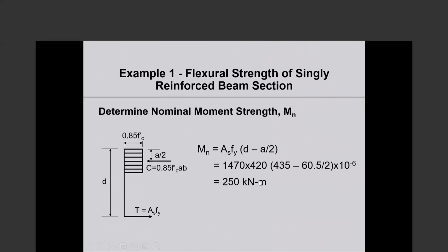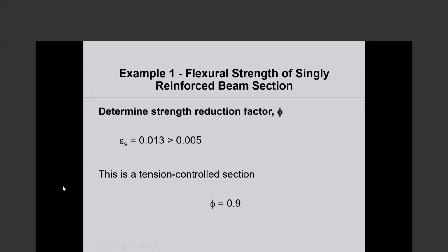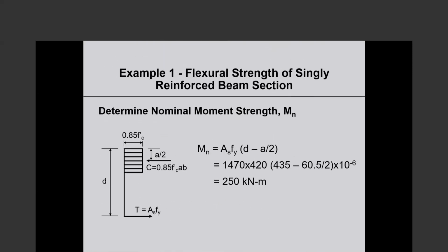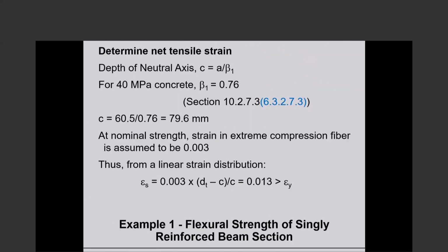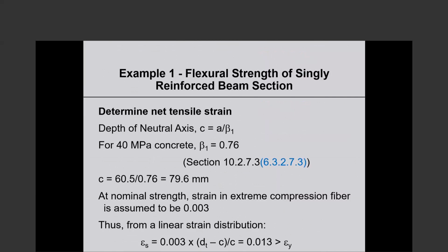Oh, sorry, prematurely. At nominal strength, strain in extreme compression fiber is assumed to be 0.003.